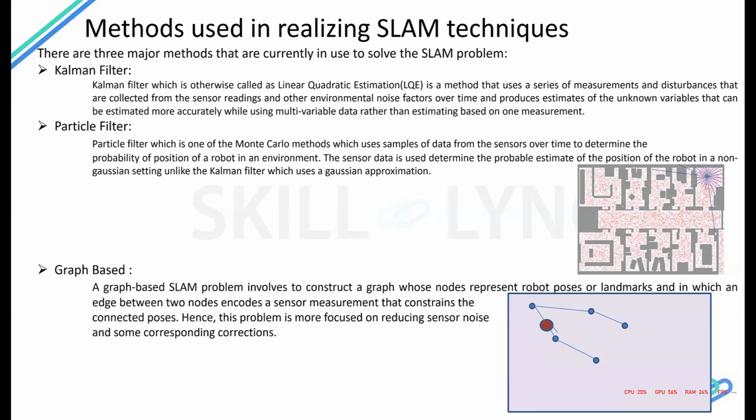You're taking it from different sensors. It can be GPS, it can be a camera sensor, it can be whatever it may be. So you have the input for the system to be a sensor input, and then you have a certain system whose structure is predefined to some extent, and you start with it. Then you have the sensor input, and you try to use the sensor input to reduce the errors and the noise coming from the environmental factors, estimate the system mathematical model, and try to correct it over time. So that is exactly what happens in the Kalman filter.